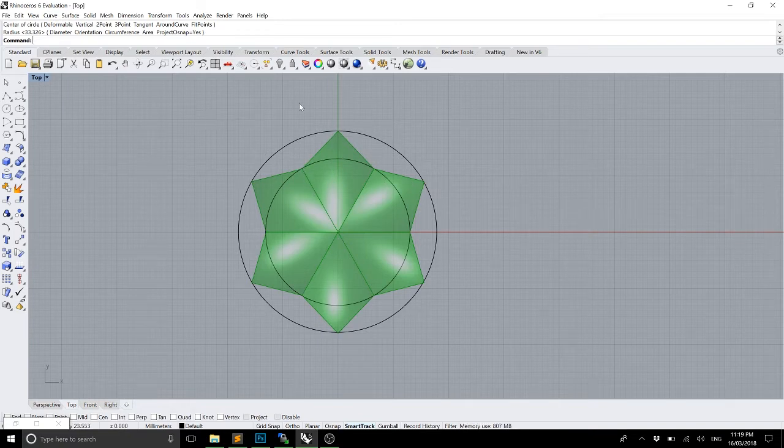And the process involved is actually then taking a circle and dividing it into points. So for example, I can actually see 1, 2, 3, 4, 5, 6. So what we're doing is dividing the outside circle by 6. So we get 6 points on the outside, and we're also dividing the inner circle by 6, but it's offset by half the division of the segment.